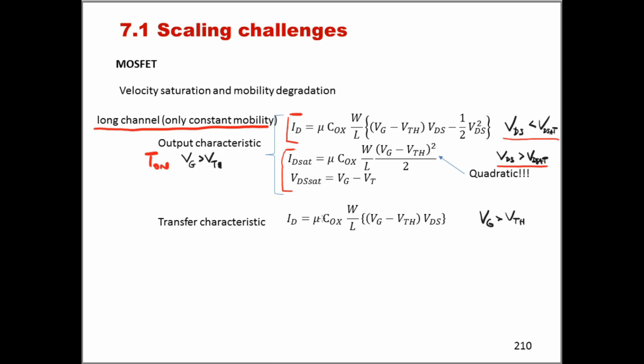Let me just point out, because I didn't say this previously. In the output characteristics of our transistor, we've often seen a parabola being drawn that was separating the linear regime from the saturation regime. This parabola is actually represented by this IDSAT. Please note that in these formulas I'm neglecting n. I'm assuming n is 1, the non-ideality factor that we mentioned previously.